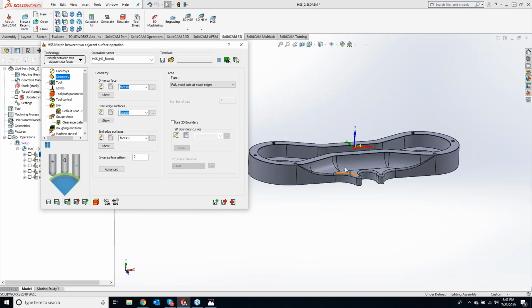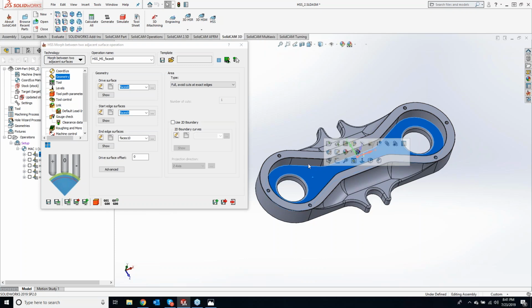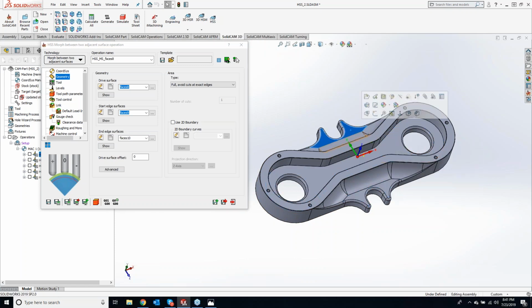So on a part like this, how I would machine this out is I would start off with 3D machining, come in here and get everything completely roughed out. Then what I would do is come in here with my HSM Horizontal to get these flat floors and vertical walls, as well as doing just an outside perimeter machining in there, and these little flat areas right here.